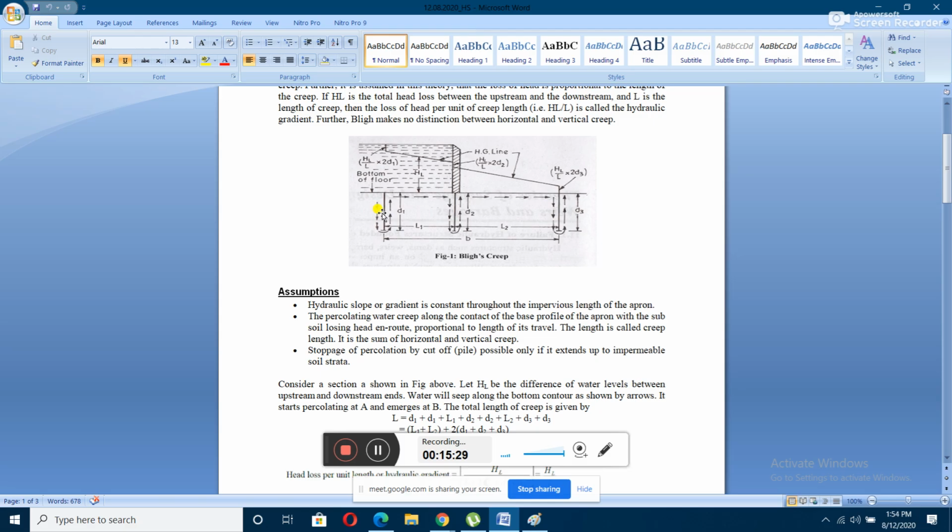Similarly, in order to provide resistance to the piping failure, we inserted another cut-off pile at the downstream side. Can everybody remember that? We did that, na? In order to provide resistance to the failure due to subsurface flow, we provided one sheet pile at the upstream as well as one at the downstream side.